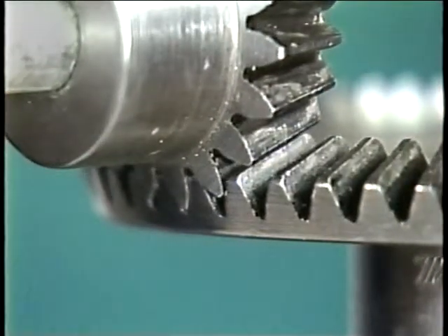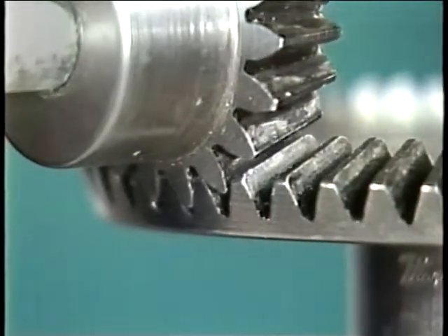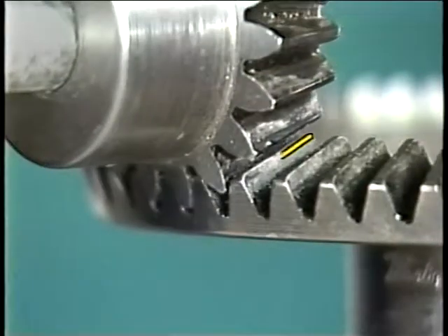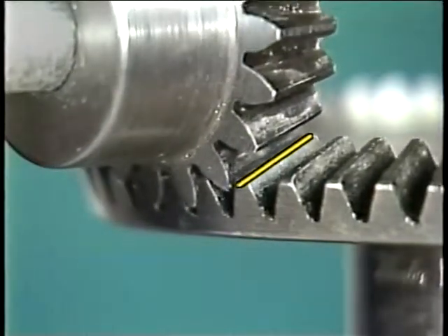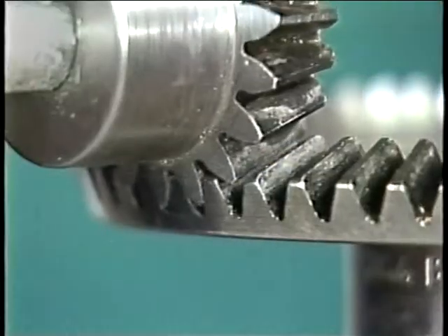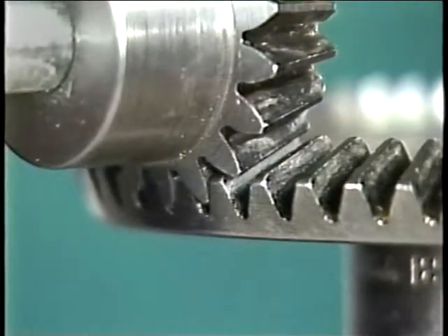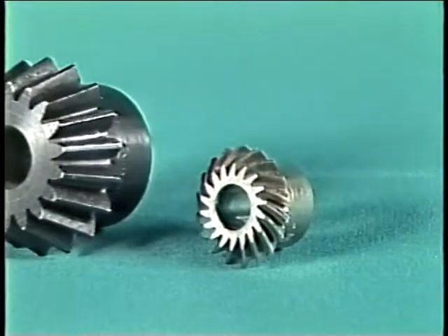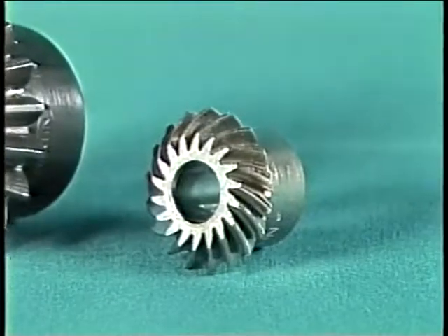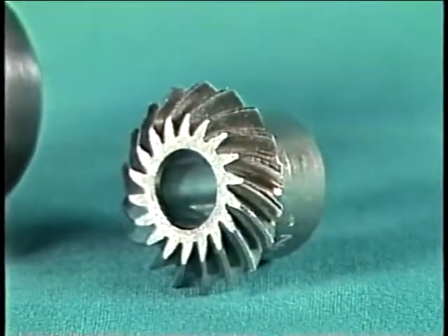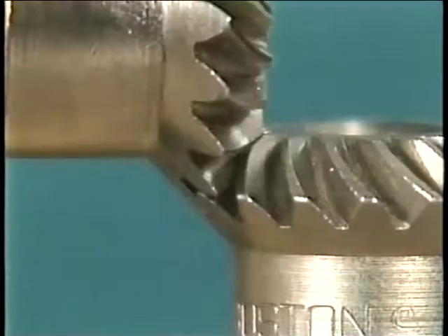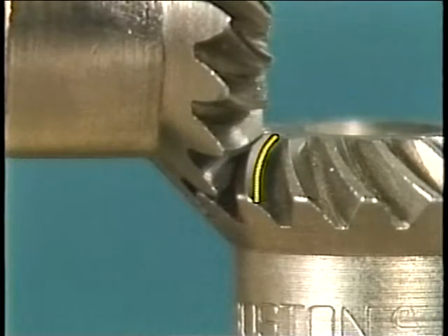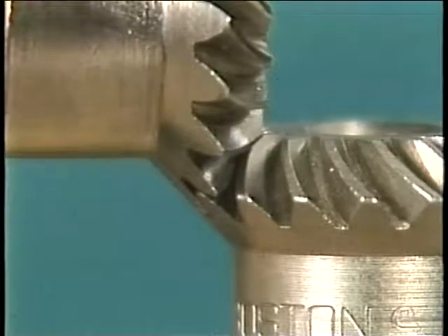Now, if you were to closely observe a spur or bevel gear set, you'd see that the gears mesh across the entire gear width at the same time. When gears mesh in this way, they may produce a lot of noise. So, in order to reduce this noise problem, and to enable the gears to carry greater loads, some spur and bevel gears are made with their teeth twisted. This design increases the surface area of the teeth and allows the teeth to engage more gradually.